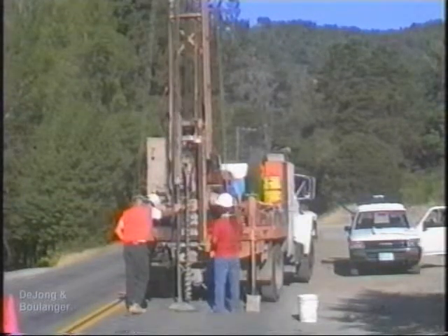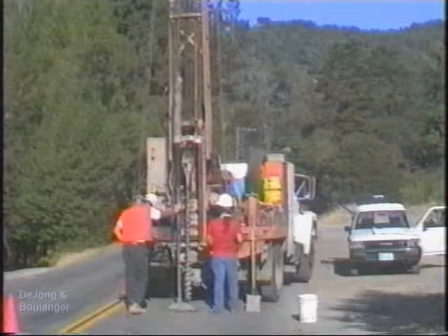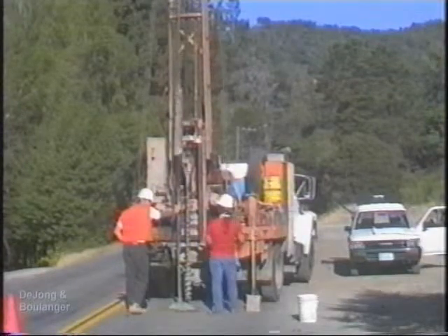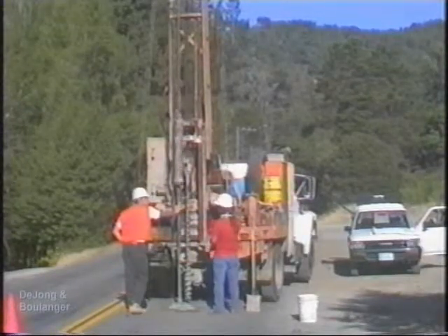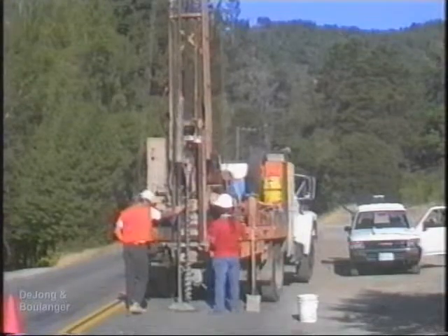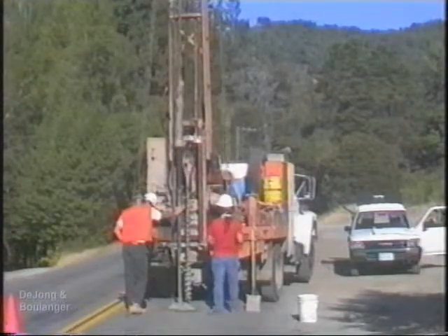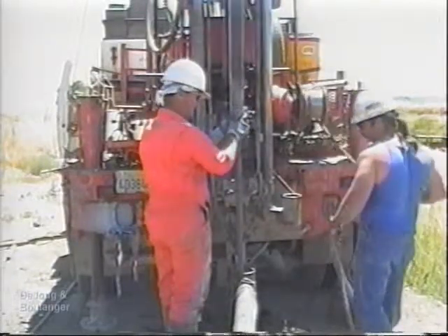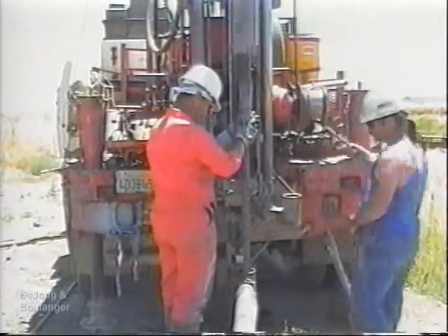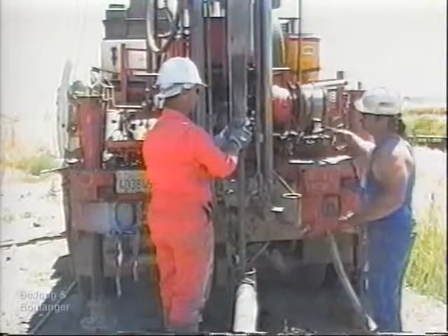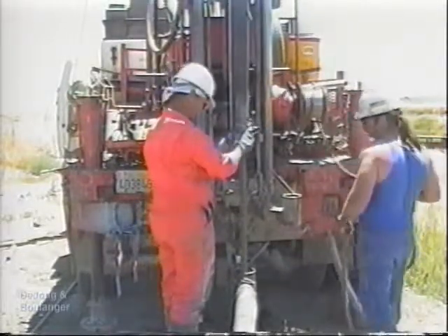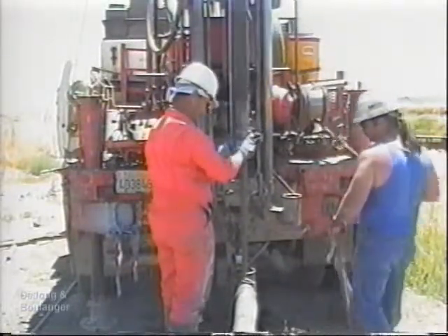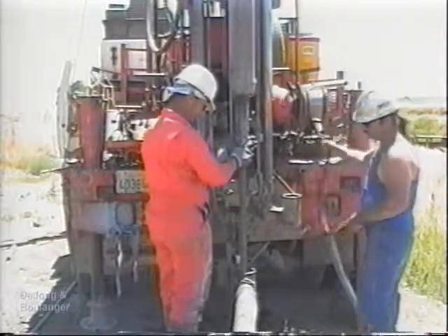If using a cat head and rope, the energy also depends on the condition and type of rope and the number of wraps around the cat head. If using a trip hammer, the energy also depends on its condition and type. The amount of energy delivered can range from 30% to 95% of the theoretical maximum. Since the N values are inversely proportional to the energy delivered, energy ratios of 30% to 95% can cause N values to vary by a factor of 3 or more.